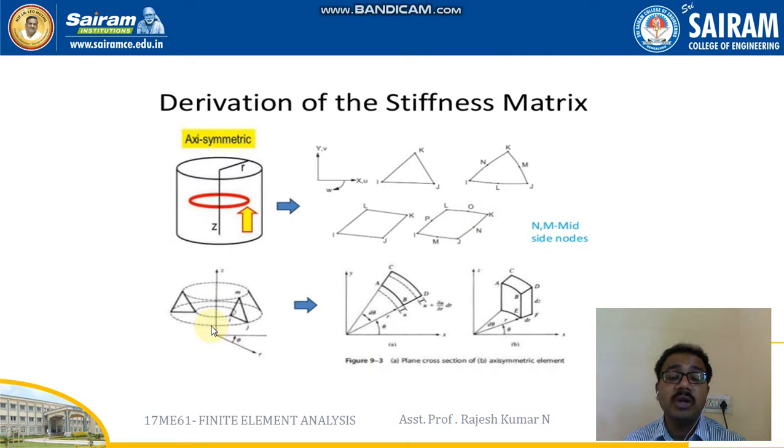Moving to this particular thing, which is the plane cross section for the axisymmetric element. You can see this particular portion, the frustum of a cone part, where I have taken only a small panel, and how the 2D view with the node numbers has been defined. You can see both the x and y axes. Theta is the circumferential angle, and r and z, the longitudinal vertical axis.